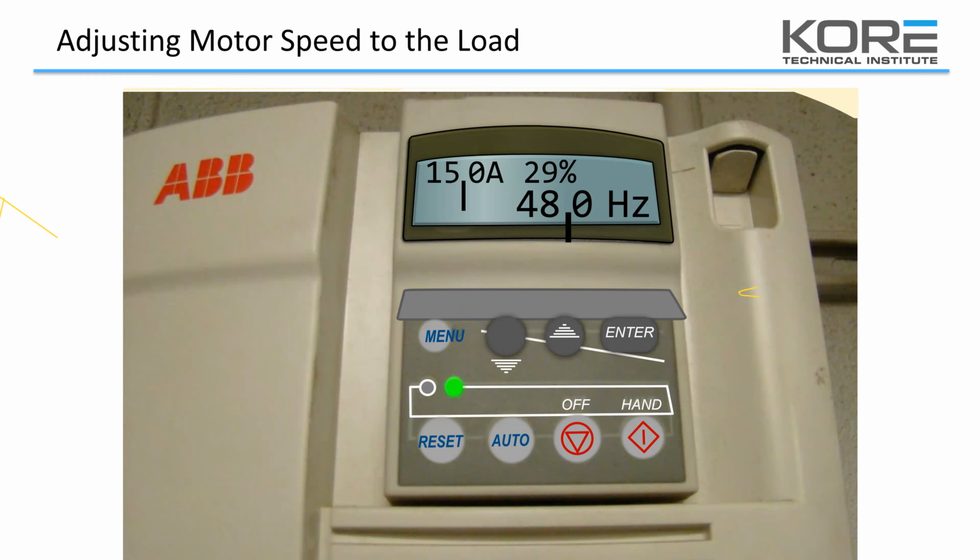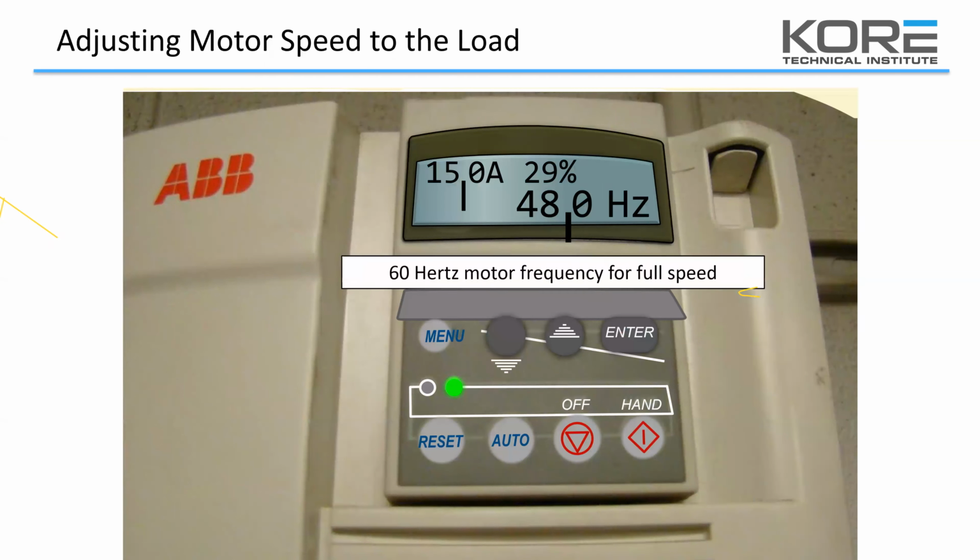Here we can see just a picture of a VFD. Here we've got a compressor running at 48 hertz, which is 29% of its capacity. That's just yet another way of doing capacity control. 60 hertz for a motor would be full speed.